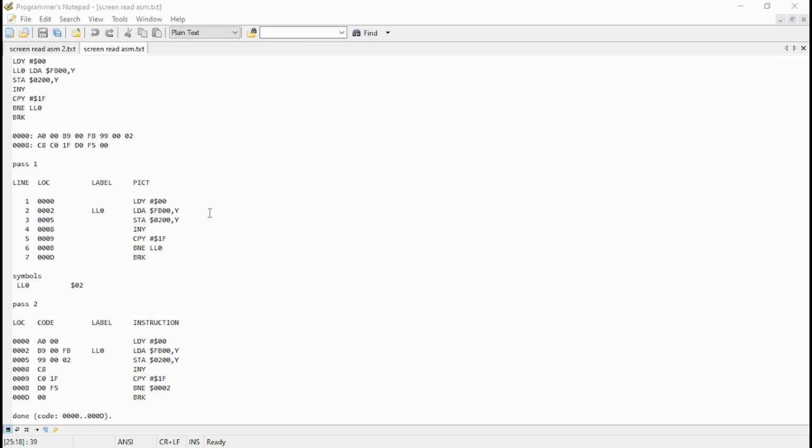So I've written a short routine to test out the CPU. I've put our test screen in ROM like we had it before, but I've put it in a slightly different memory location because I want to put our program to read the screen at the lower part of the ROM. If we take a look at the program in assembler, that's what we're doing.